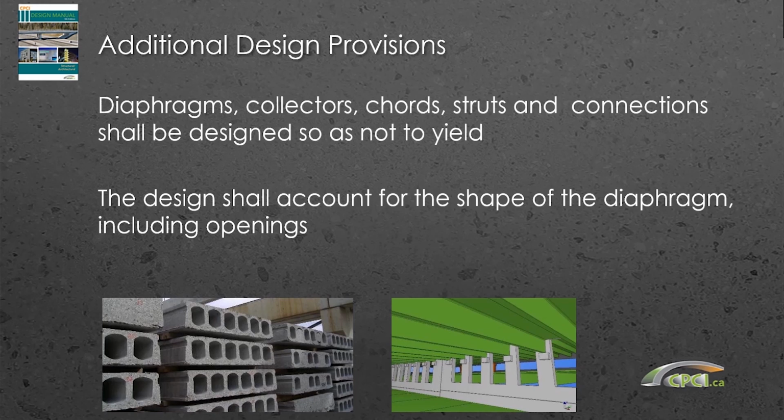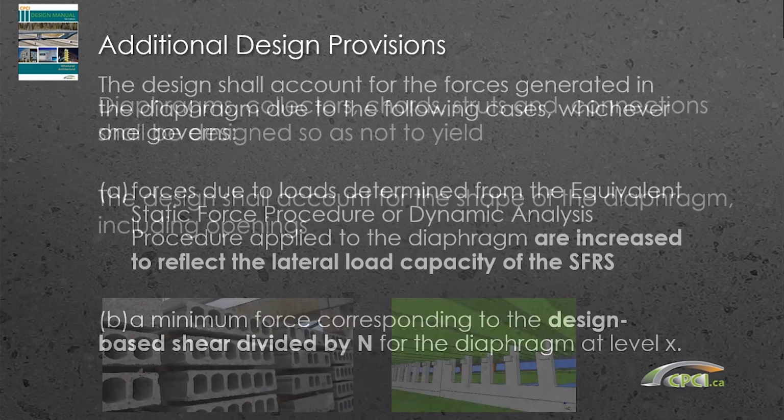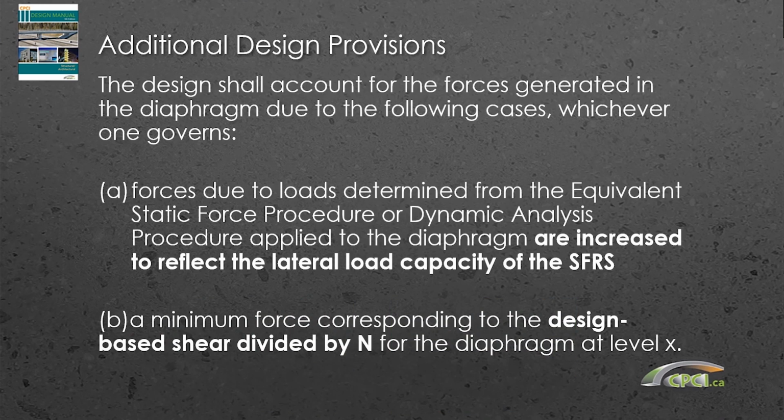And then some additional design provisions for diaphragms. Need to make sure that the connections don't yield, and the design obviously needs to account for the shape of the diaphragm, including openings. Just some additional reminders, not new, but just reminding everyone, you need to increase your forces to reflect the lateral load capacity of the seismic force resisting system. So you determine your loads, but you also need to look at your capacity as required by the different provisions in your concrete standards and the NBC.